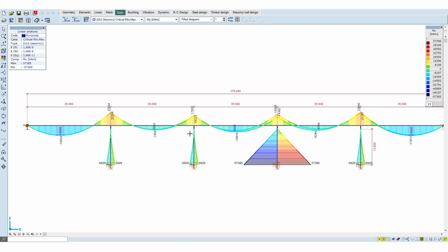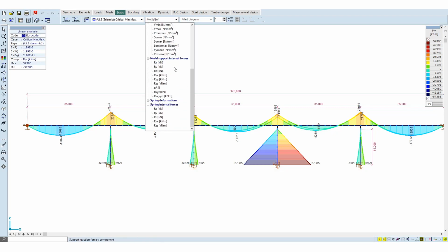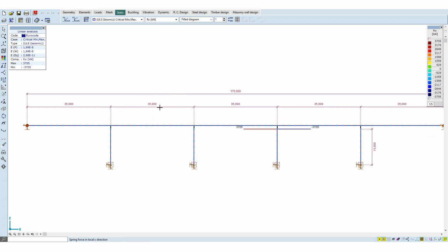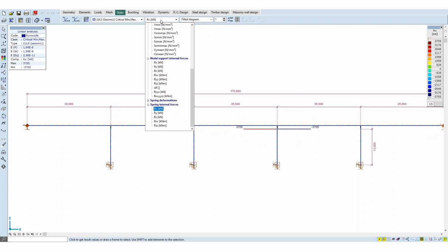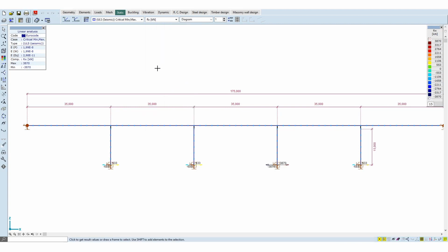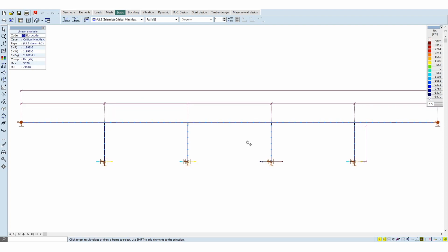First, we check the longitudinal bearing force, and then the base shear force as the reaction force at the pier foot. We can see that the maximal longitudinal bearing force is only 5% smaller than the maximal base shear force at the bottom of the bridge. This shows that including the weight of the pier just slightly changes the total base shear force. The mass of the vibrating system is mostly provided by the deck.